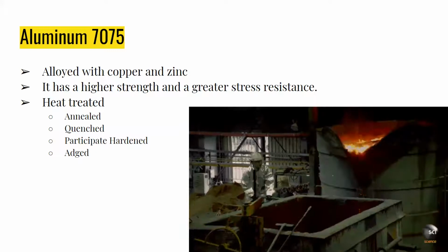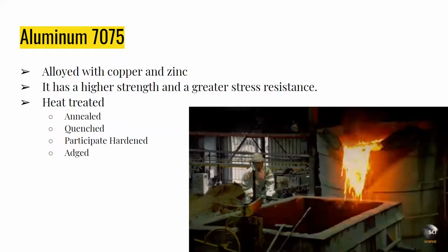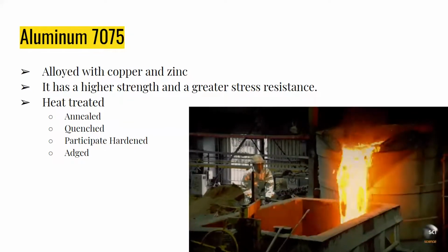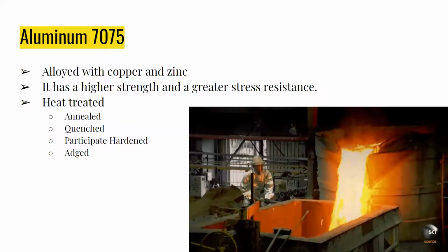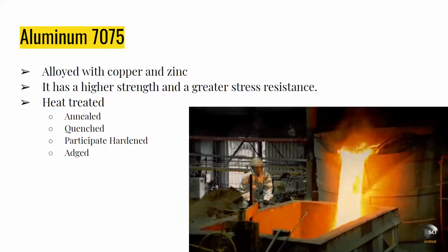This alloy's annealing temperature is between 700 to 900 degrees Fahrenheit. The best mechanical properties, though, come from the aluminum being annealed at 900 degrees Fahrenheit for 2 hours, then quenched in water. After that, it should go through the precipitation hardening or aging process. Here, you have to decide whether you want the alloy to have a T6 or a T73 strength rating. Both treatments end with air cooling so that the precipitates can form and the grains can grow.